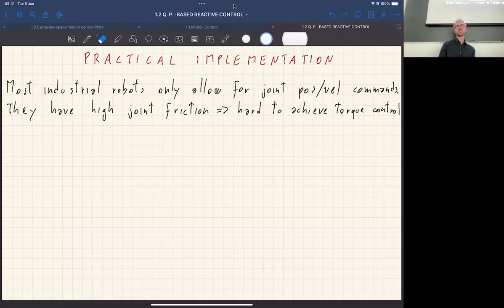That's not impossible. For the tolerances of the gearboxes. Yeah, when they push, they have to be precise, and therefore there is friction. Again, the high joint friction is not desired. It's a consequence of the gearbox.